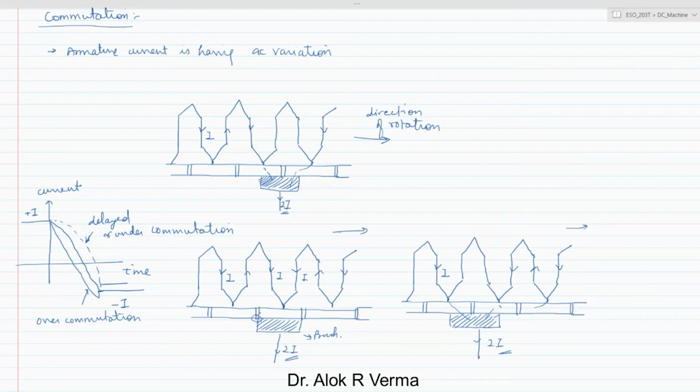So there are various methods which can be used to improve the commutation, basically to avoid the current problem. That is resistance commutation, voltage commutation, or compensating windings, which are used for commutation problems. Commutating poles or interpoles are used for commutation problems. You can read in the reference books that interpoles are the narrow poles constituted inside the machine in between the main poles.